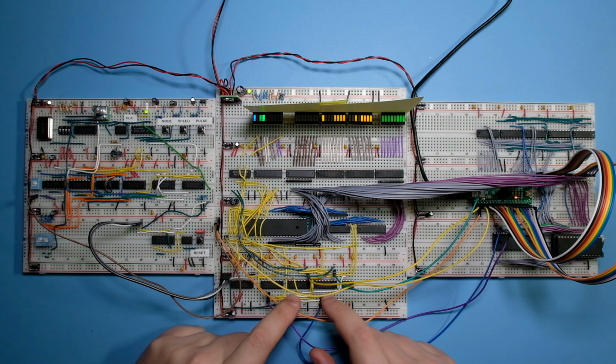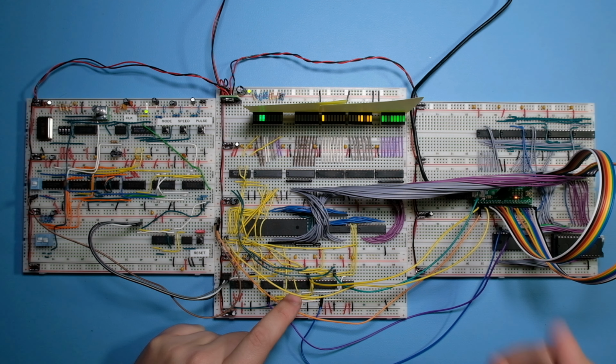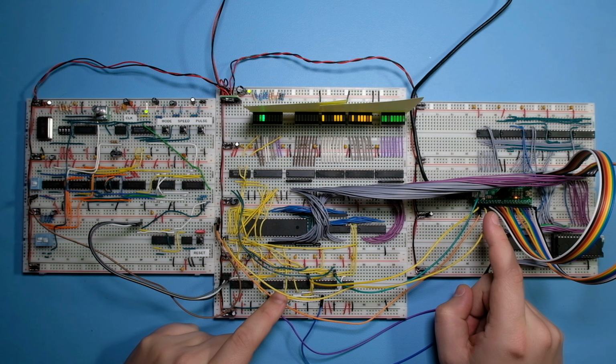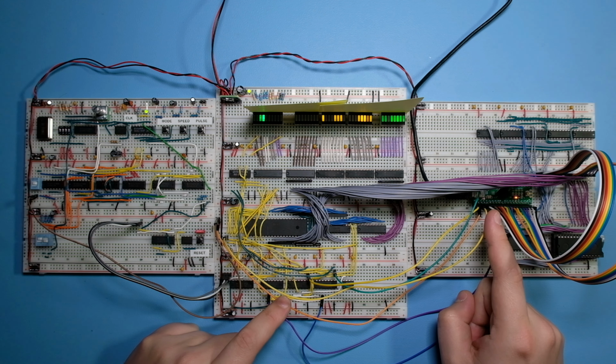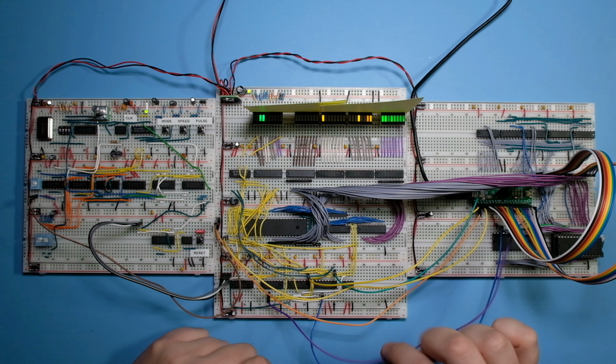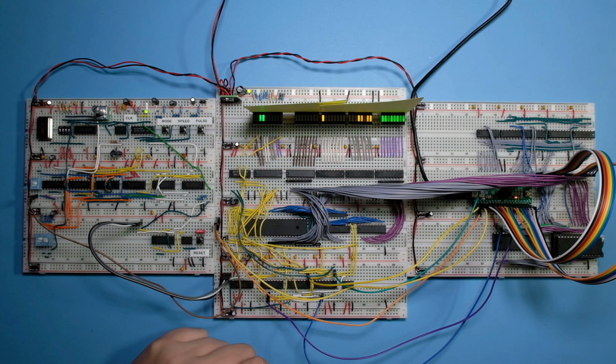Okay, so in this video, we've added the new VA and sync signals to our glue logic. We've added them to the monitor so that we can see when we are doing opcode fetches and we can ignore dummy cycles. And we also started working on a rework of the read and write signal, but we haven't finished that yet. That's going to be the subject of our next video. So in the next video, I will finish the rework of the read and write signal. I will fix the timing. This will probably involve some reworking of the clock in order to introduce multiple phases. So that's going to be pretty exciting, I think.